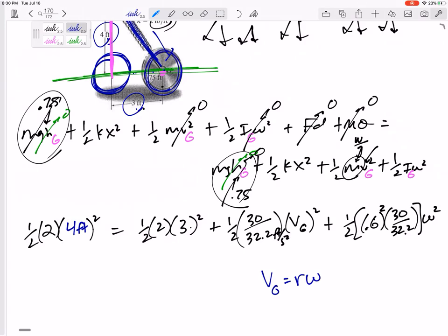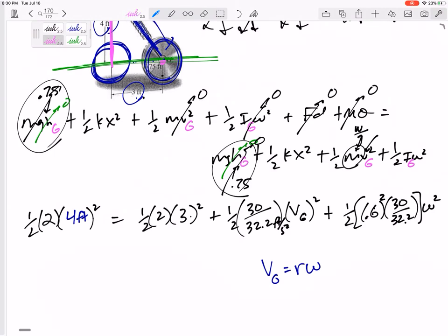Well, the disc is not rotating about its center. This is a wheel that is rolling without slipping. We've talked a little bit about wheels. I don't think we actually did this, but for wheels, where is the instantaneous center of a wheel? Where's the place on the wheel that has zero velocity? Down here on the ground. There's my instantaneous center of zero velocity. So this R, the distance that G is away, G would be right here, and the instantaneous center would be down there at the bottom.